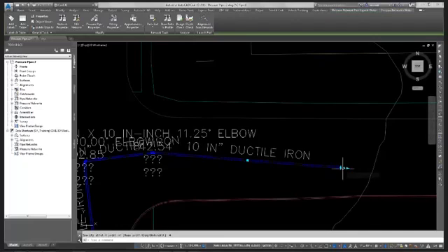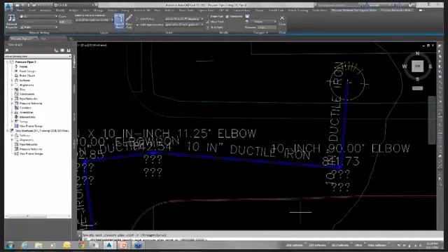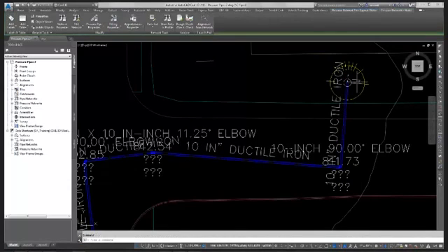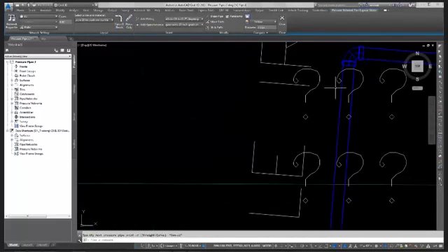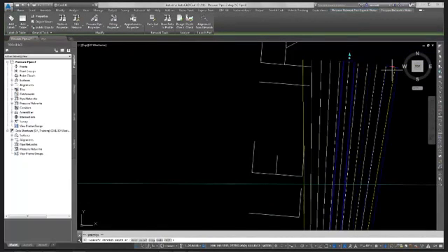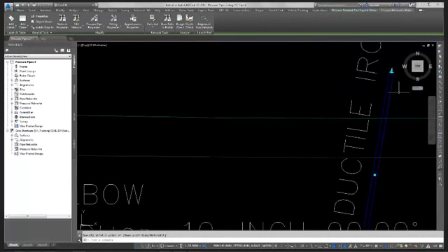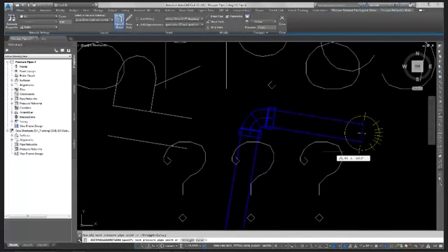I can hit the plus sign at the end of a pipe, and it brings my compass right back up. So now I can say, oh, yep, now I need to continue on over there. Stop, plus sign, come out again. Erase, erase. Maybe I want to put my deflection in first and then add my pipe, just to make it more realistic in the world because of that 5 degrees of deflection that's allowed in each pipe and still have it sealed.